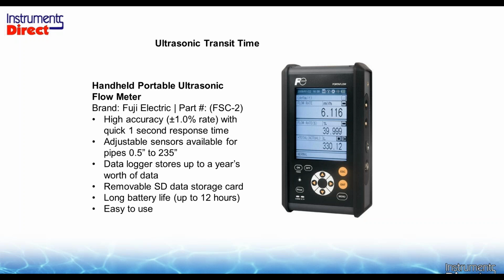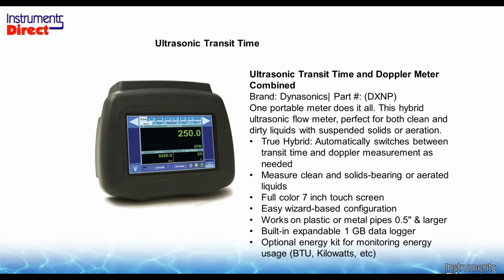So select the portable ultrasonic transit time flow meter that suits your need. There are some that are in a big NEMA 4 weatherproof suitcase that you want to leave sitting in the mud, or there are ones that are handheld. You can walk around and go from pipe to pipe to pipe to do your water studies.